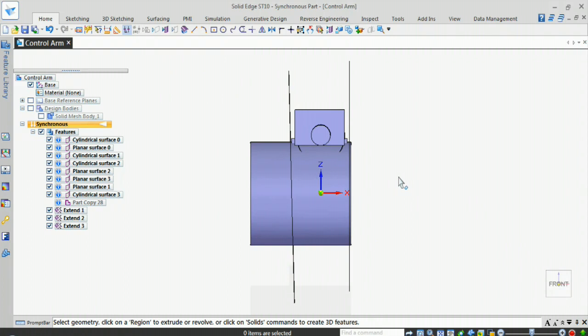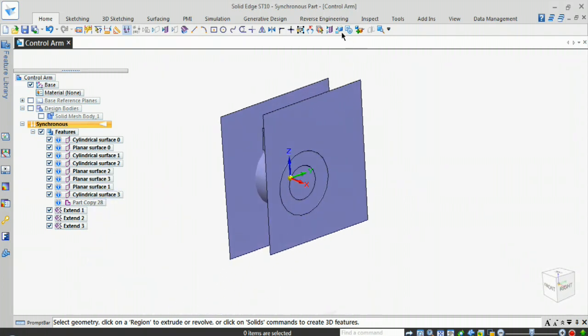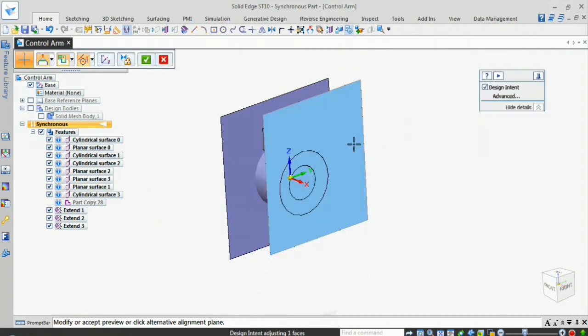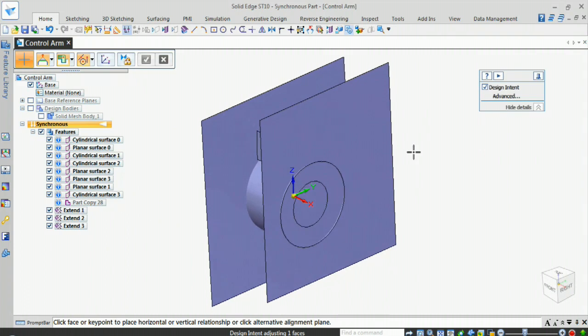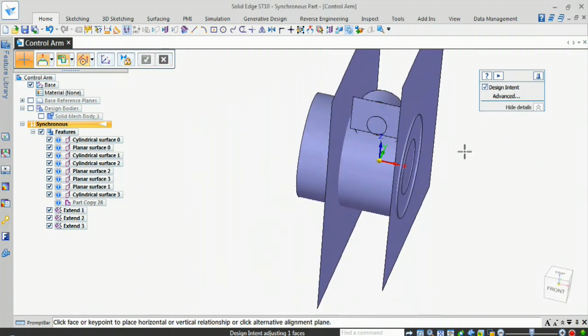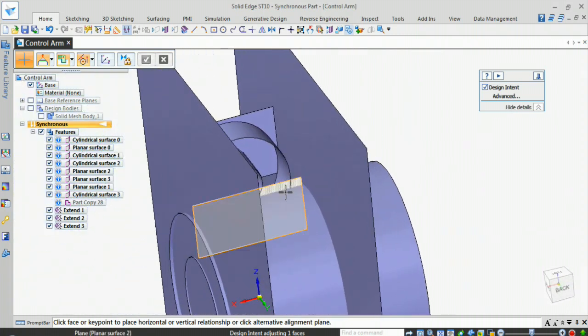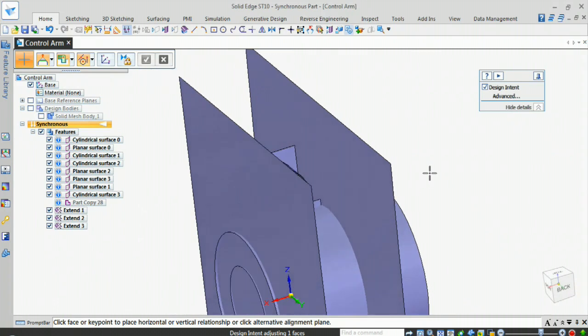You can notice that the back face is angled. This is by design and I want to leave it that way. But all other vertical faces have to be perfectly straight. We can tap into modeling functionality here as we're working in Solid Edge. Synchronous technology will take care of this for us. In particular, the face relate command works great for that purpose.